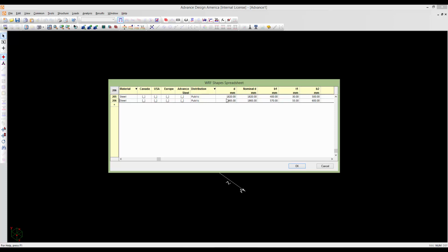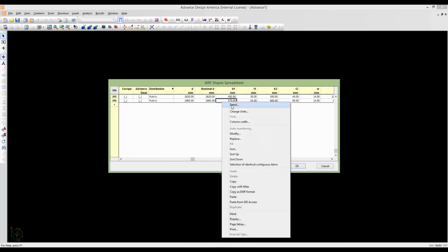As you see, we have a much greater height here, and the width of the flange is also different. So the second section is stronger than the first one. I'm going to use the second one as portions 8 to 11. The first one will be portions 1 to 8. You will see those right away. To check the details of this section, I can check it here.